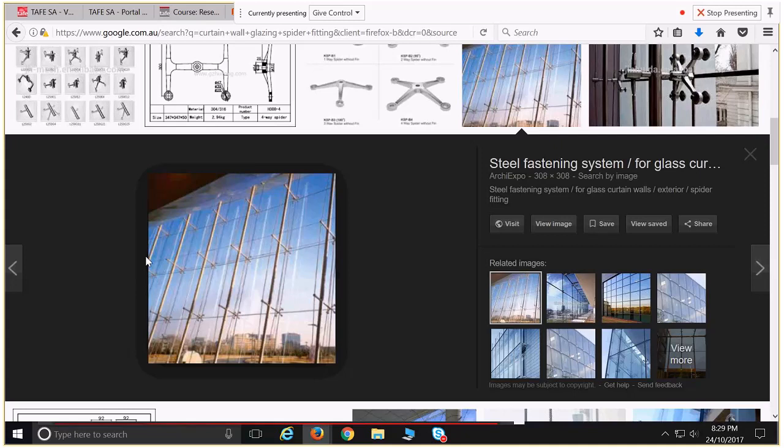So that wire being tight, it's putting pressure onto the back of that, because when we get wind on there, primarily it's going to be a racking force applied on the side. Yes, we will get suction at times, but not to the same extent. And so to resist those forces, we have that wire at the back there.